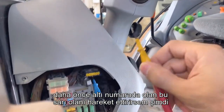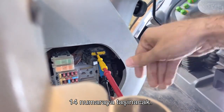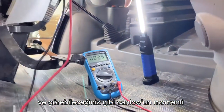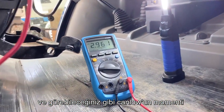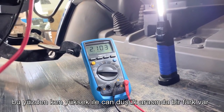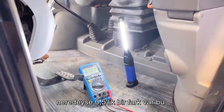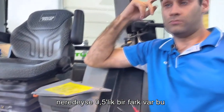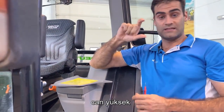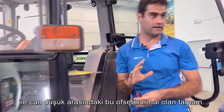If I move the yellow one that was previously in number 6, now it's going to be moved to number 14. We've got CAN low, and as you can see, CAN low has 2.10. So there is a difference from CAN high to CAN low. There is a difference of almost 0.5. That's this offset from CAN high to CAN low. It's the normal one. Okay.